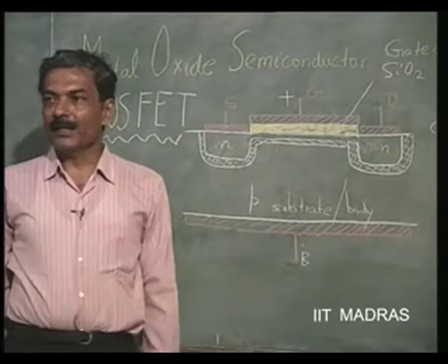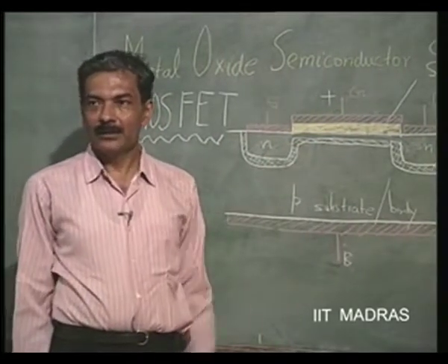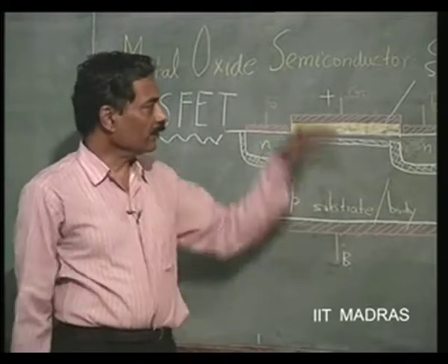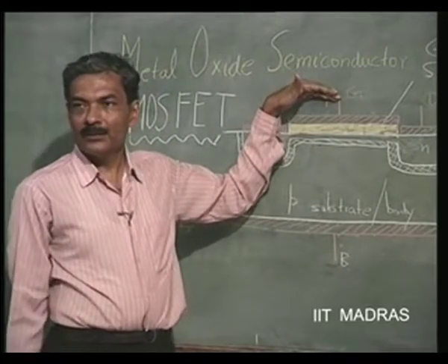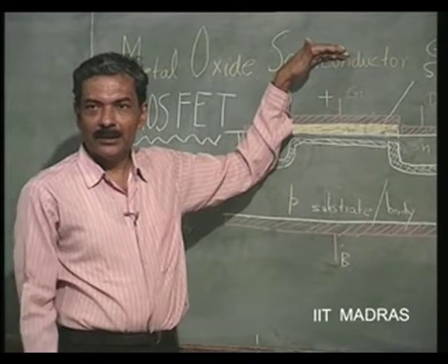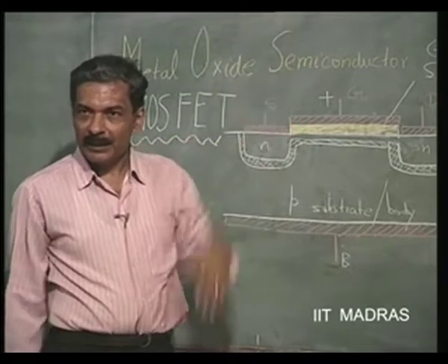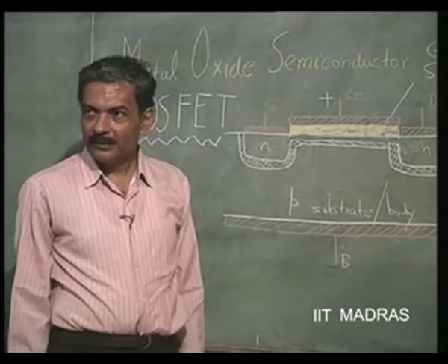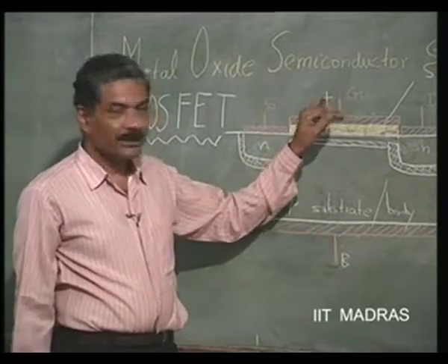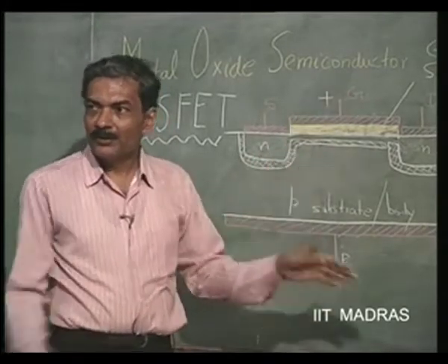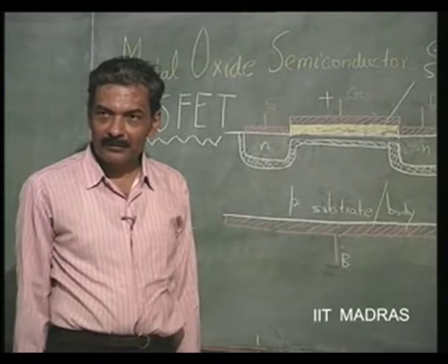The width of the channel, the depth in this case, can be easily controlled by this voltage. The higher the voltage, the wider it will be, right? So, as to compensate for the positive charge here, it has to open up wider. Right.